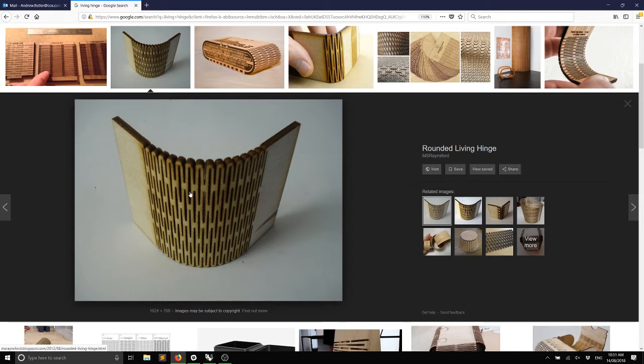what's going to happen when we do that to this? We've got a line here, but we're going to a point. There's a problem. As I laser cut to a point, anything that goes to a point is going to get infinitely close to each other, as it gets closer and closer to the point. So as you get closer to this point, you're going to start to create a lot of heat, a lot of surface area, a lot of very thin material that will eventually begin to disintegrate, okay?